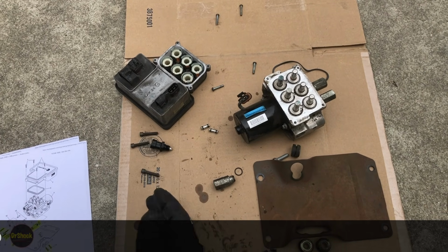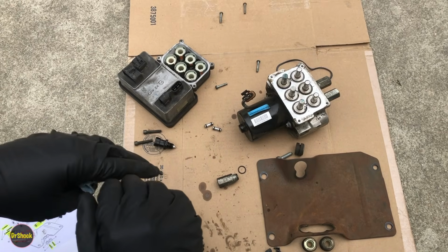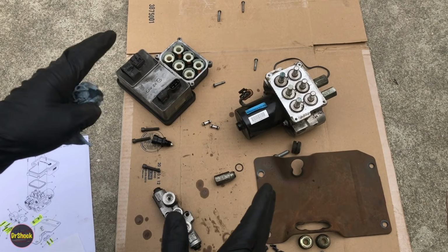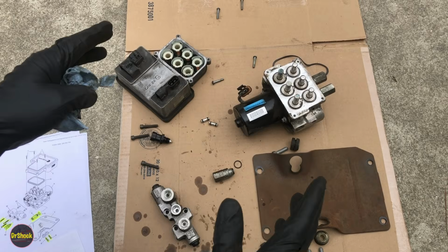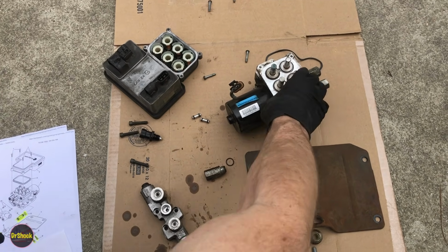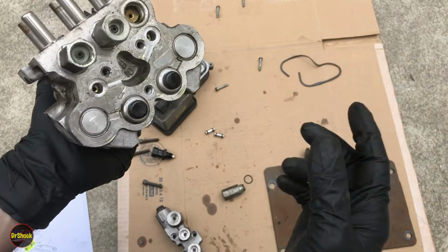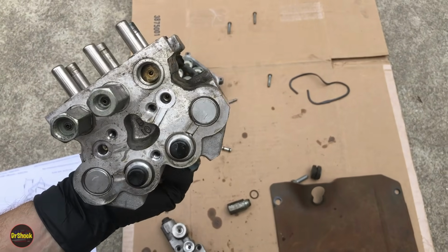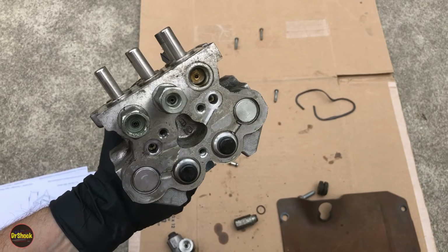The only other thing I could tell you is when you go to the salvage yard, understand that they drain the brake fluid in most places. So you're going to see the master cylinder empty, but make sure it's not full of rainwater, because if it's full of rainwater and it's been sitting without a hood, that water is going to run into this BPMV and there's going to be corrosion inside and the unit's trash.